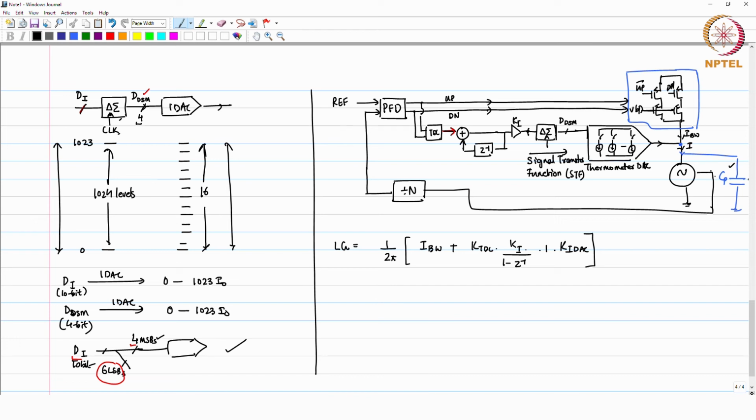then we find out what is the output frequency. Okay. So, here we come up with this logic that in a steady state, when all the currents are fixed, there is only the noise and the variations, I can model the VCO using its equivalent resistance, and this particular current goes through this R VCO times Cp, that is the pole.